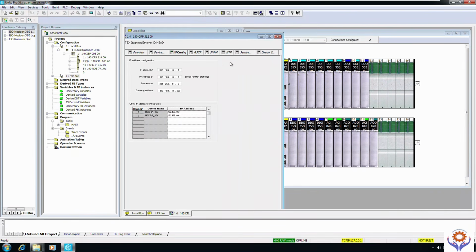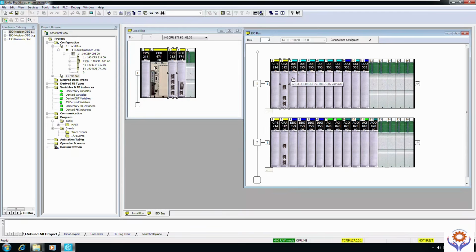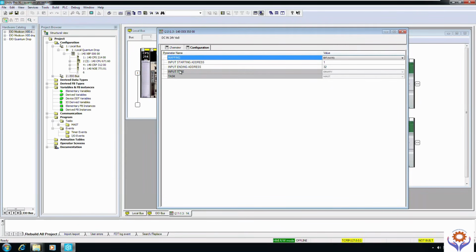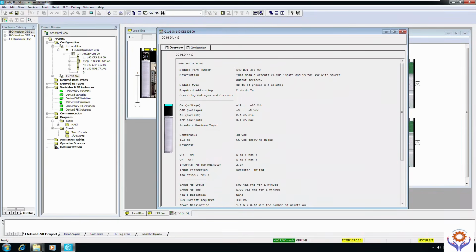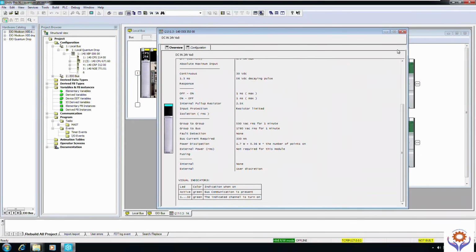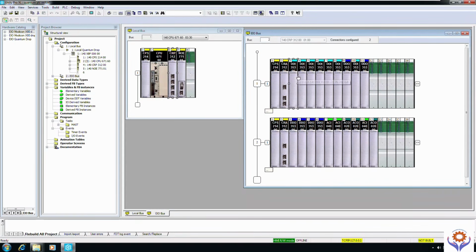It is configured with the CRA address 192.168.1.3, which it takes by default. And if we click the IO address, you can find the IO address starting from 1, that is %I 1 up to 32 for the first slot, and it takes this by default at the initial stage. If you need to change the address, you can change it directly from the starting address in this place itself, but in our case we can use this default %I 1 to 32.